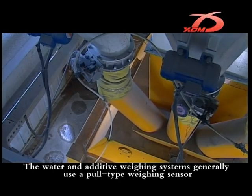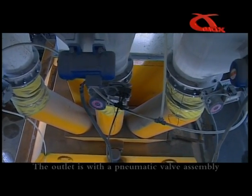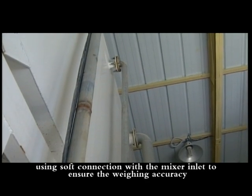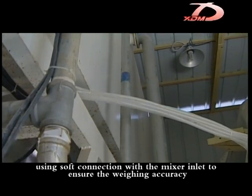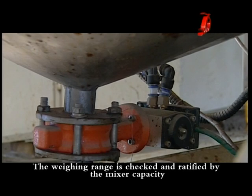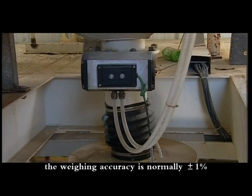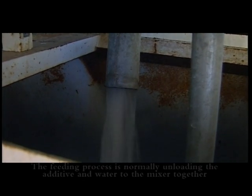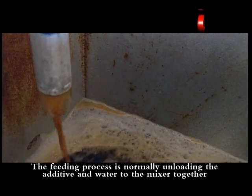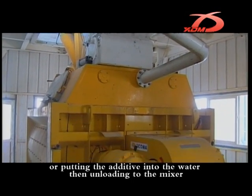The water and additive weighing systems generally use a pull-type weighing sensor. The outlet is with a pneumatic valve assembly, using soft connection with the mixer inlet to ensure the weighing accuracy. The weighing range is checked and ratified by the mixer capacity. The weighing accuracy is normally of plus or minus 1% error. The feeding process is normally unloading the additive and water to the mixer together, putting the additive into the water, then unloading to the mixer.